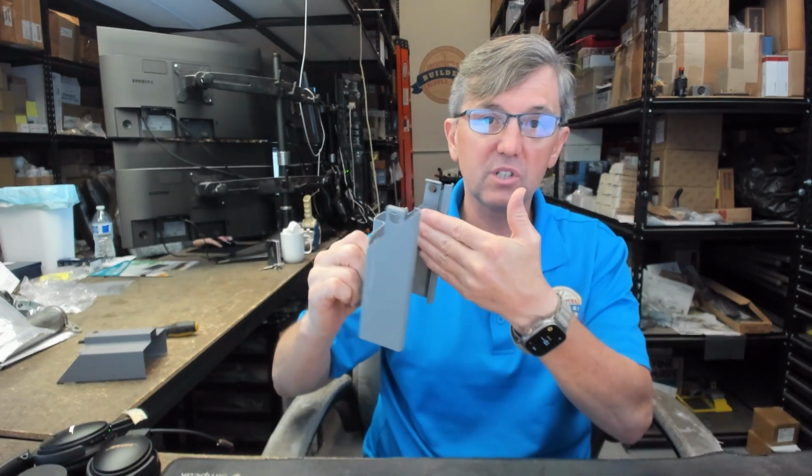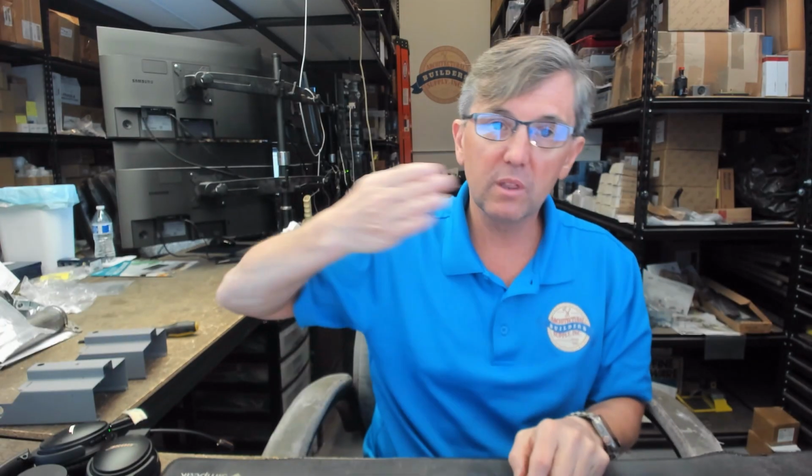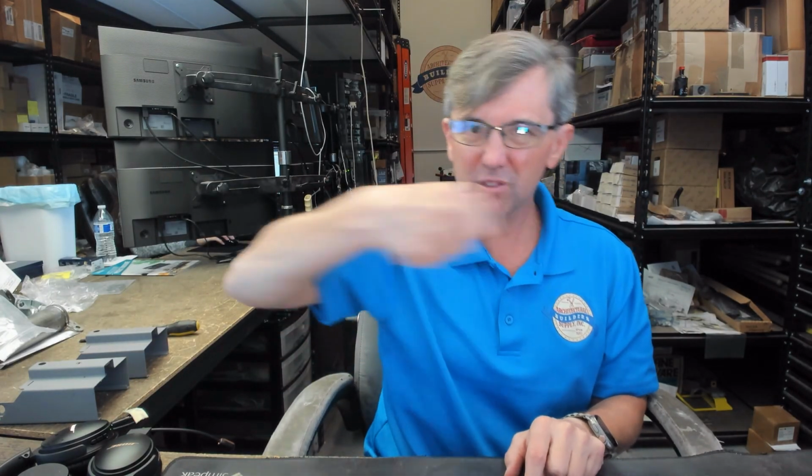so no studs are up. It's a big open space. Frame comes in and it's bolted to the floor, shot to the floor. Studs are brought up to everything, and then when the drywaller comes in, he wants to shoot the drywall in behind the frame. Yeah, they would like for that to slide in easier, and that back bend return will permit that sliding in easier. And plus also when they cut the drywall with a drywall saw, it's no longer 5/8 there. It's 5/8 further in the sheet, but it's not 5/8 out there because they've just ripped through it with a saw. So that flares out so it gets fatter, so they've got to jam it in.